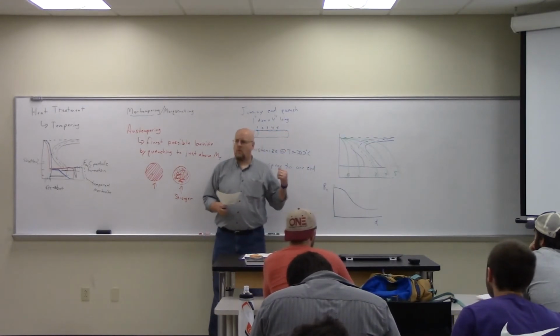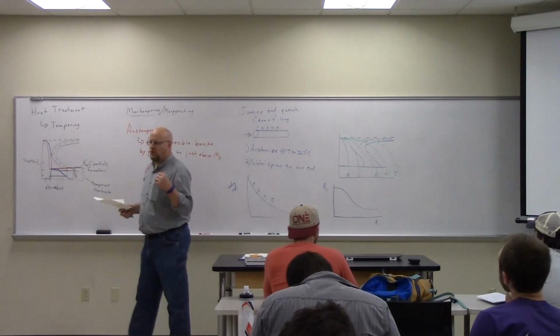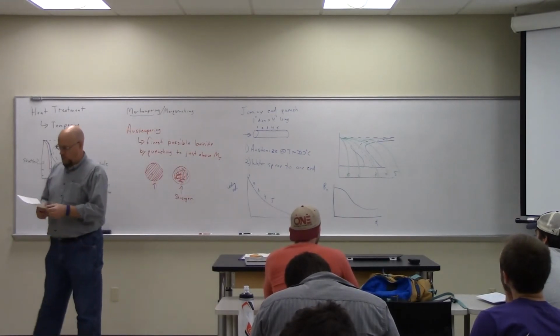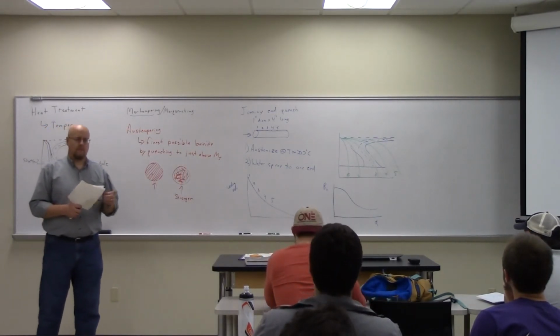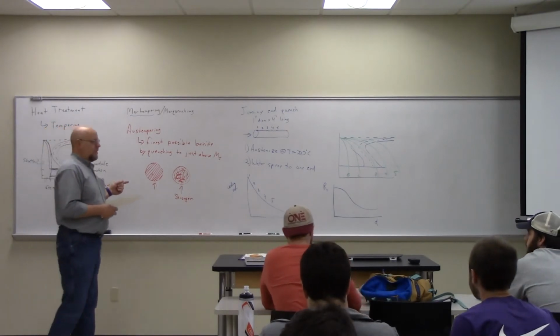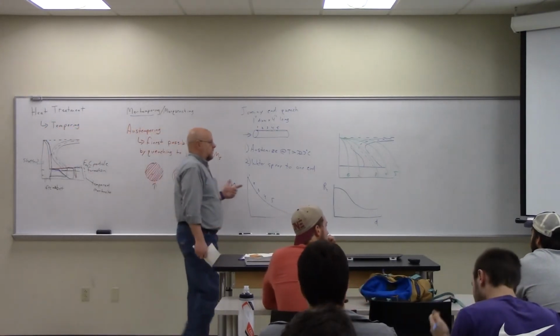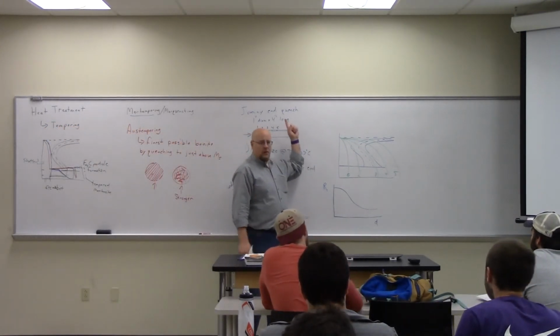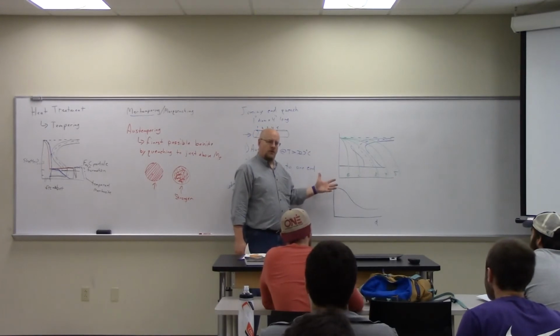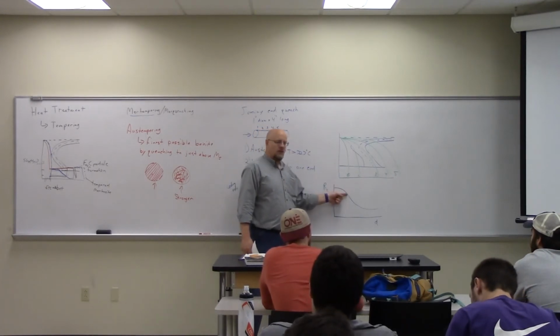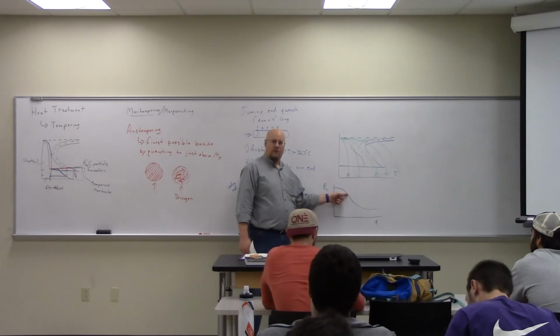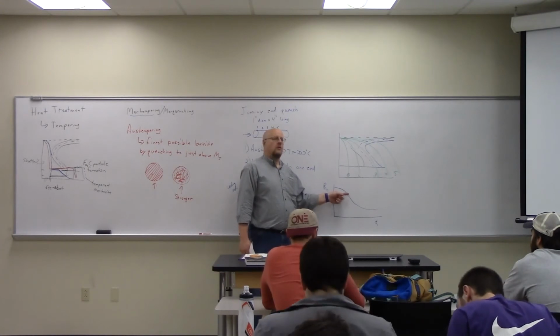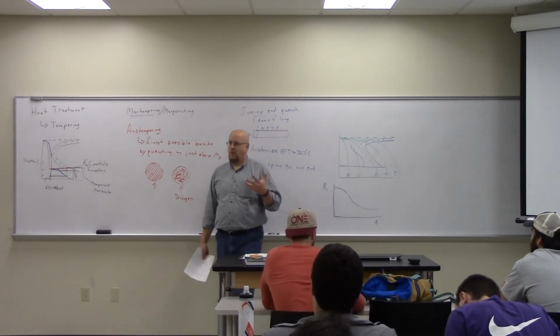High hardness on the front end where it was quenched, low hardness in the back end where it wasn't quenched. So based on the end quench geometry for my particular material, I can say I need a hardness of at least this much. Therefore, I know what kind of quench rate to use to get my material that hard.